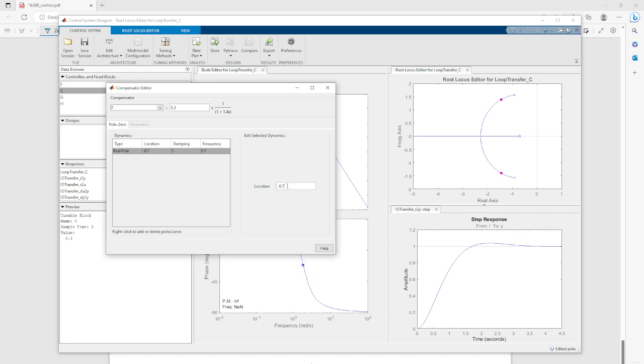So, and here probably one thing, if you don't do the canceling exactly, right? So you place the 0 at minus 7.5, it's also okay, right? You're basically adding some lag here to compensate for that 0. Here the lag is a little bit too much, so you basically have this over-damped behavior. But the point is, placing it around 0.7 is a good idea.